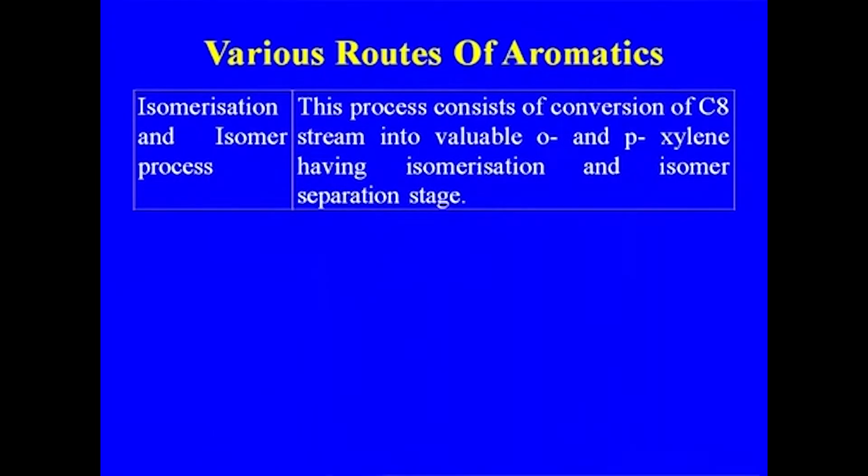Isomerization and the isomer process: as I told you, the isomerization process is also an integral part of the paraxylene process. This process consists of the conversion of the C8 stream into valuable ortho and paraxylene, having isomerization and isomer separation stages. These are the two stages involved in the case of isomerization.